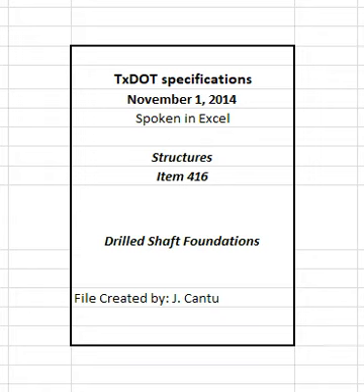Use ice or other concrete cooling ingredients to lower concrete temperature, or run additional slump loss tests at the higher temperatures. Slump loss testing will be waived if anticipated time of concrete placement is less than 90 minutes. Use mineral drilling slurry that meets the requirements of Table 3, as determined by TEX 130E. Determine pH of slurry by TEX 128E or pH paper strips.